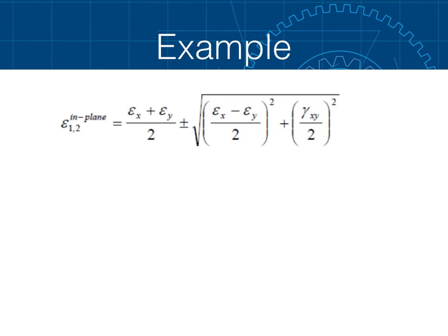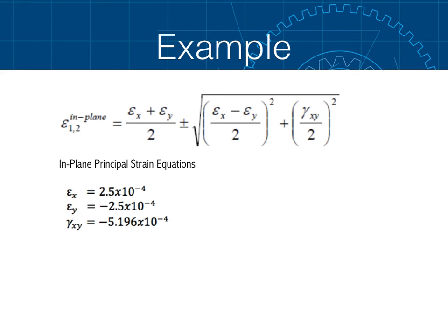Using the in-plane principal strain equation, we can now calculate what those principal strains are, because we have values for epsilon x, epsilon y, and gamma xy. Here are those values again. Let's input these calculated strain values into the in-plane principal strain equations.